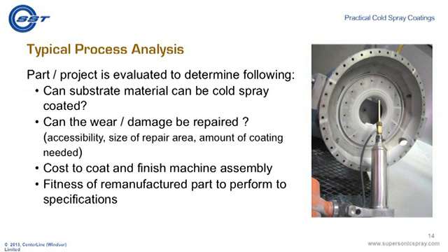Can the wear damaged component be repaired? Is it accessible? What's the size of the repair area? How much coating is needed? Can the part be mounted, rotated to the proper orientation? We'll look at the costs, and we will examine the fitness of the remanufactured part and compare it to original specifications. Again, CenterLine has the capabilities to help you validate your application repair.